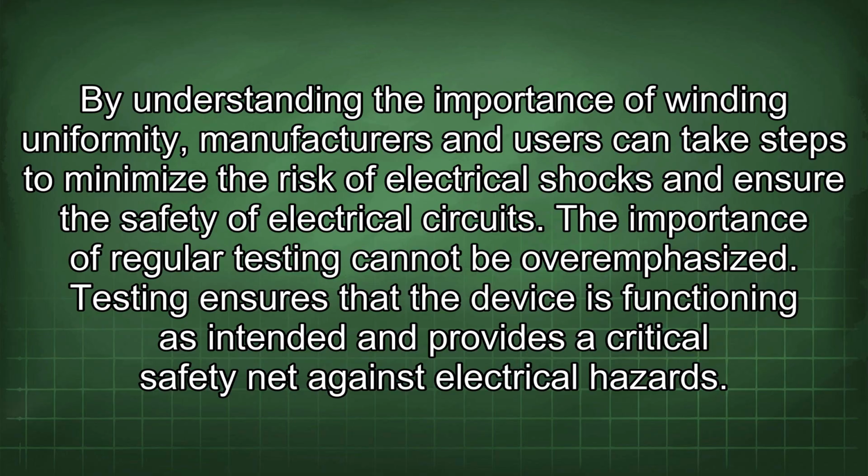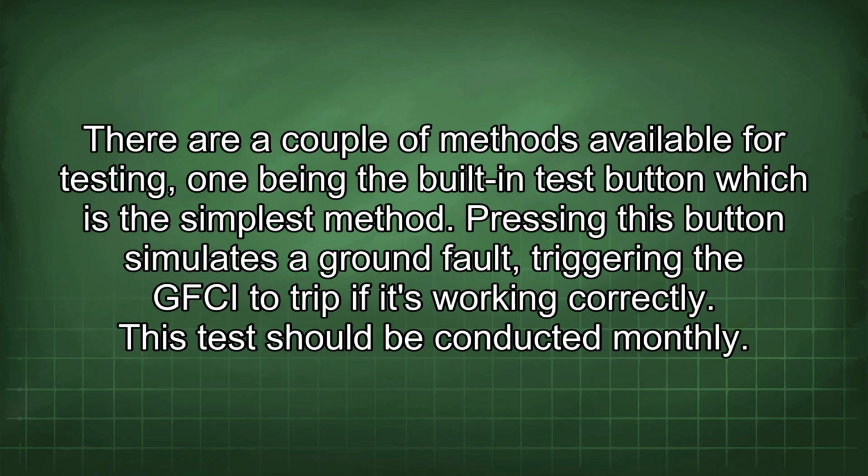The importance of regular testing cannot be overemphasized. Testing ensures that the device is functioning as intended and provides a critical safety net against electrical hazards. There are a couple of methods available for testing, one being the built-in test button, which is the simplest method. Pressing this button simulates a ground fault, triggering the GFCI to trip if it's working correctly. This test should be conducted monthly.